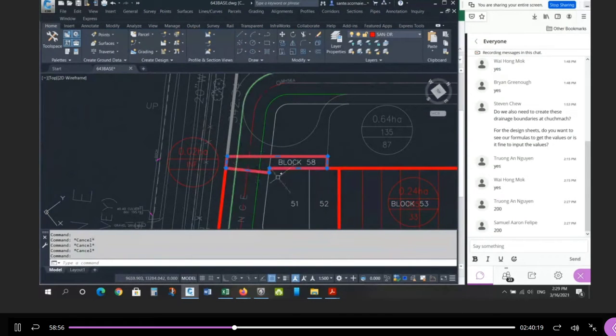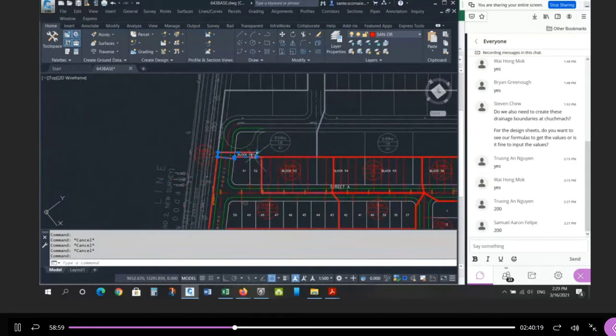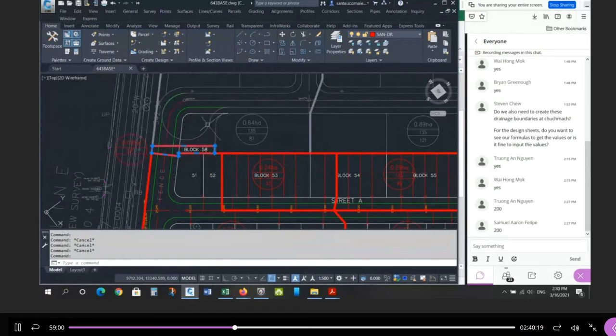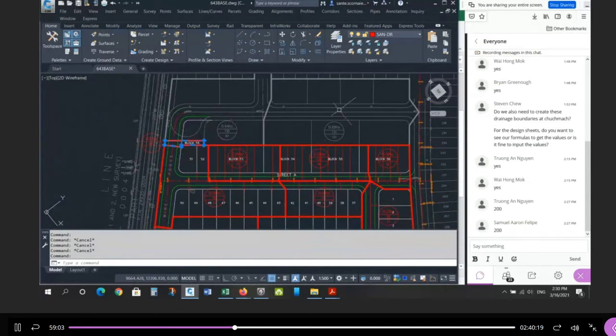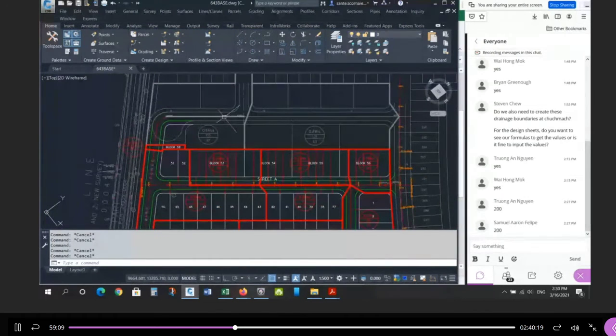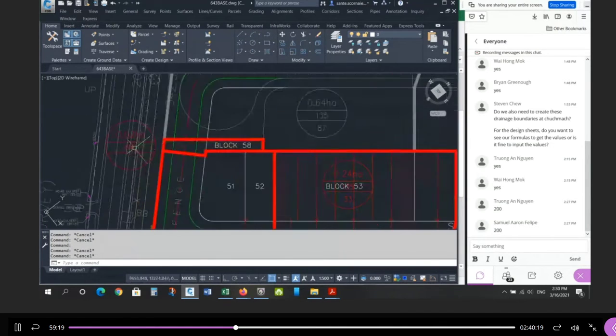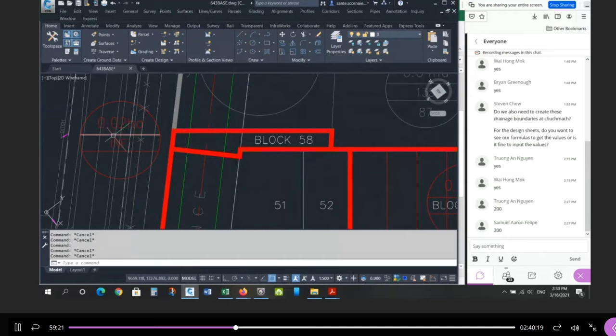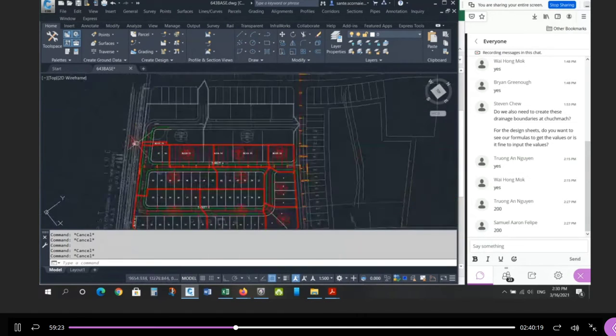And this area, although there's no houses connected to it, is going to contribute infiltration to this pipe and this pipe. Okay. So I need to check: if I increase the area going through these two pipes, are these two pipes going to be negatively impacted? Do these pipes have capacity to take a little more infiltration area? And that's something you need to check. Okay? So the infiltration area is an additional 0.02 hectares.